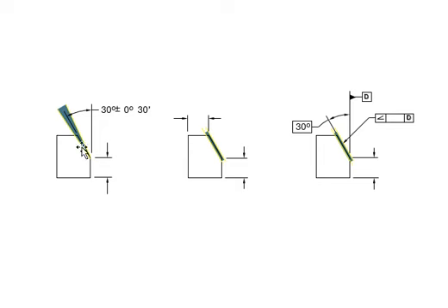But then, of course, a polar tolerance is a wedge shape concentrating only on this inclined surface. For that one, it's like the surface is completely a parallel zone, and that's what we're talking about. Even though we do the extension, there is a difference between this and that. So I try to teach you all the time to make sure when you are looking at it, you know what you're seeing. So don't see this picture and then get the wedge shape polar tolerance, because we're not talking about that for the parallel zone.